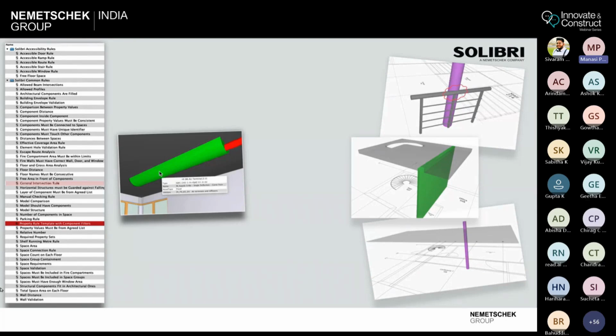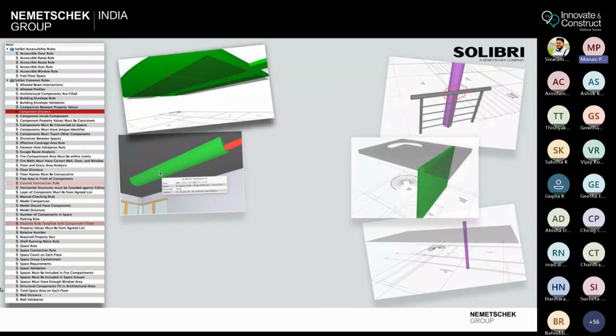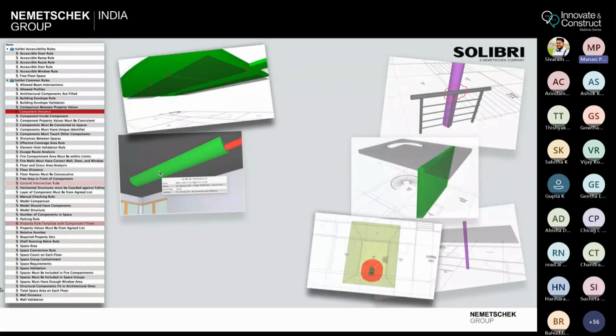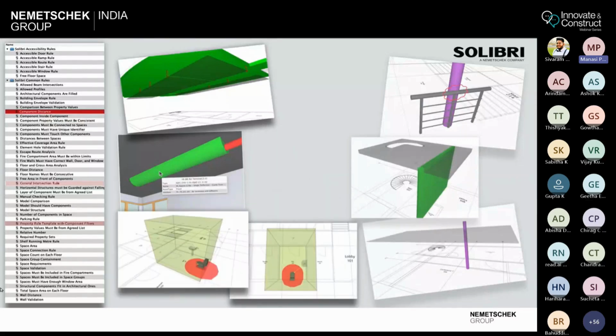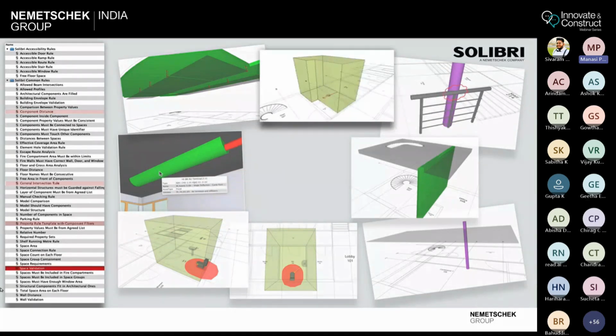Further, when we talk of component distances, they can be all the vertical clearances, horizontal clearances. This is an example of fire sprinklers at horizontal clearance. Then another example is the constructability area around a given construction object, something as small as a WC or as big as an AHU. It needs a constructability space clearance around it, which is the free area or the space validation for doing the construction in a certain manner and having the mobility to use that space effectively.